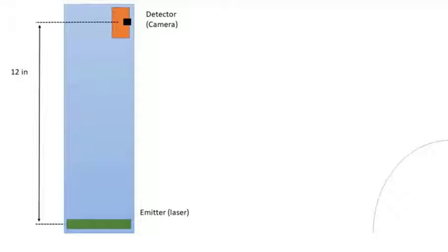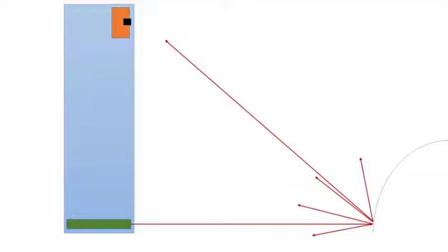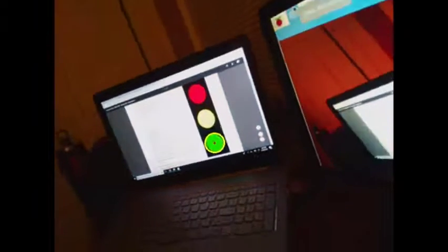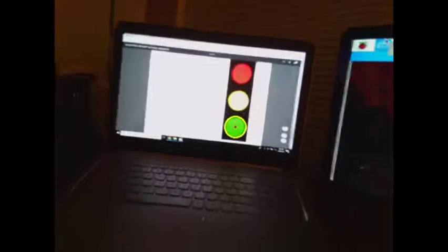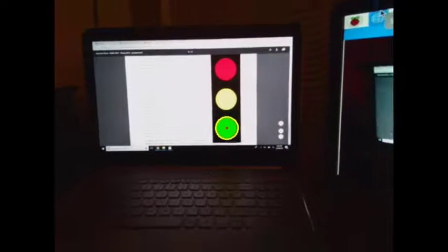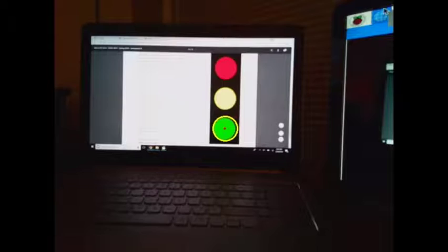My LiDAR does not use this technique. My LiDAR uses the distance between the color, using OpenCV, of the red line and the pixels from the center to determine the distance, and using our known geometry of the LiDAR itself to find this range to give us the picture of the object. As we can see in this example, which was done during the semester, the green light on the stoplight is being tracked by OpenCV programming. My LiDAR uses the same principle of finding the color of the red laser and finding the distance between it and the center of the camera.